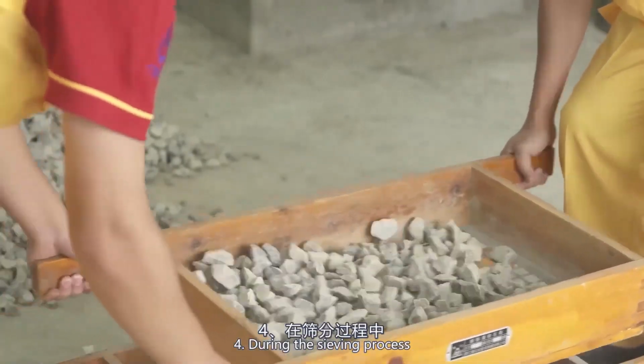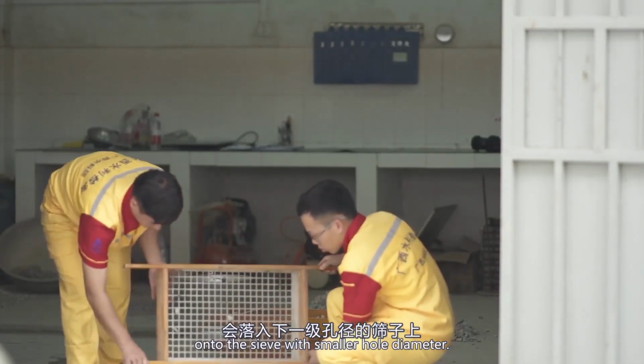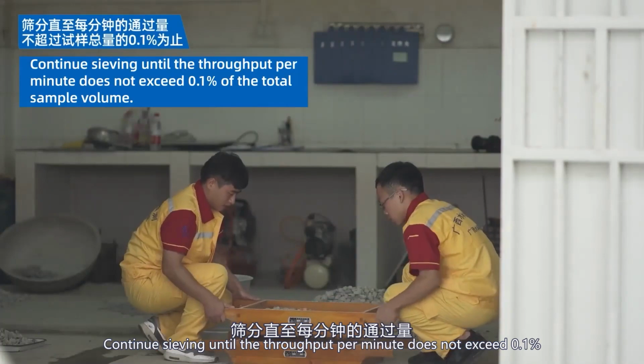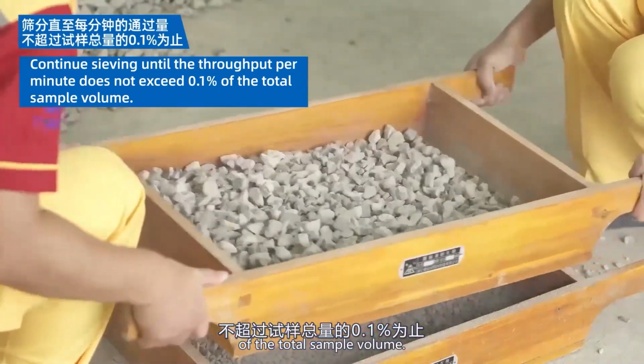4. During the sieving process, the stone smaller than 20 mm falls onto the sieve with smaller hole diameter. Continue sieving until the throughput per minute does not exceed 0.1% of the total sample volume.